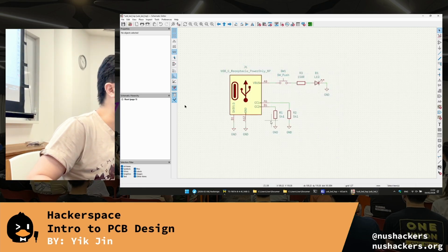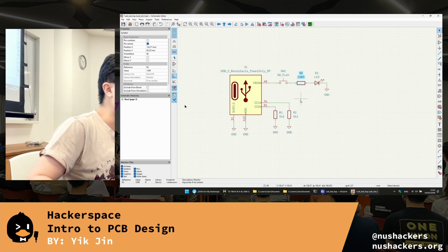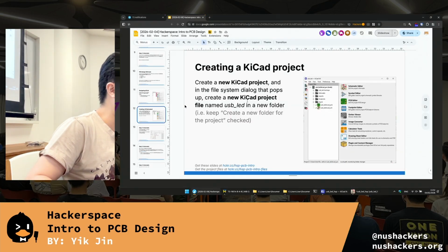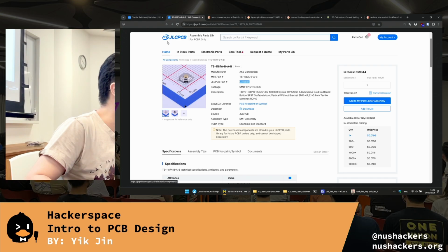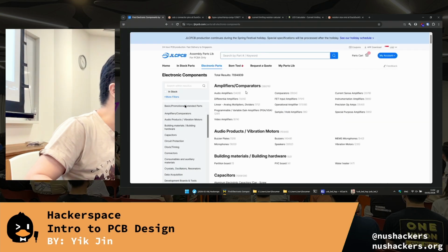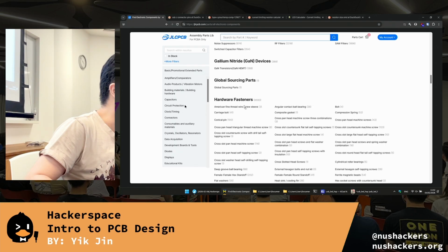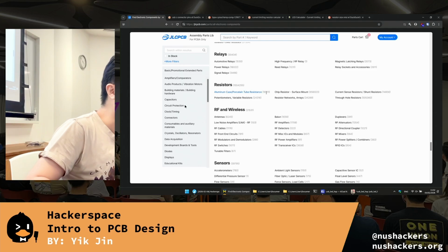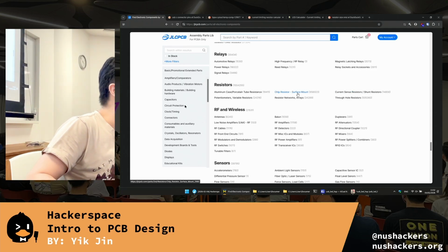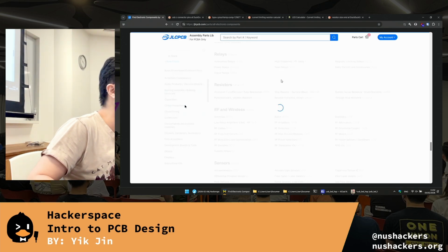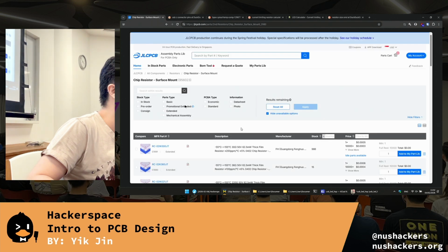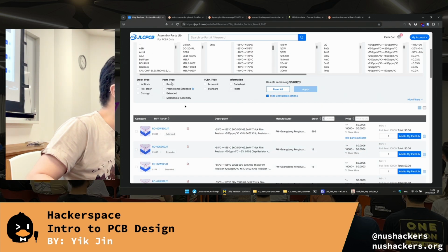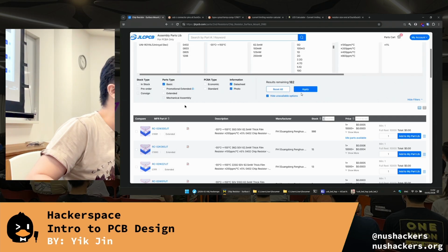Now I'm left with resistors, right? And I guess the USB. Yeah, so the resistor, I can just take this. Let me search resistor. Resistors are under a category called resistors. Okay, there we go. Surface mount. I want a surface mount resistor. So it's chip resistor, surface mount. Again, I want basic, datasheet, photo.